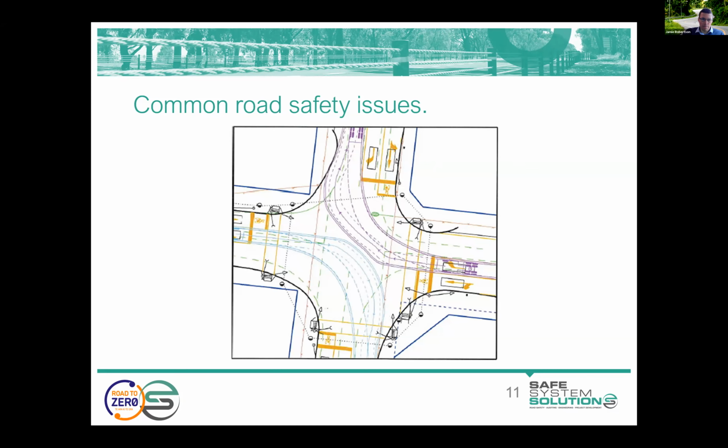So it can be fudged and sometimes is by designers. This appears to be a particularly constrained location, and it looks like a bit of a back to front design, where an intersection has been drawn within the available space and then some swept paths have been dropped on the top to make it look like it will work.